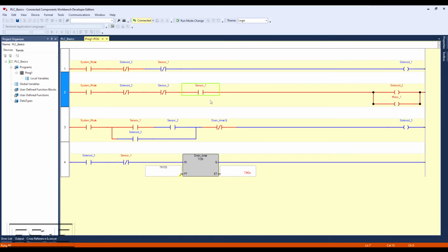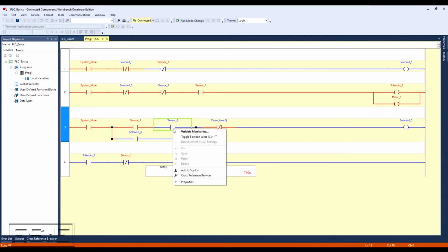Now we are mixing and adding our second ingredient into the tank. We are going to continue to fill until sensor 2 is turned on. When sensor 2 turns on, it will shut off all the remaining equipment and open solenoid 3. Our last step in our sequence was to leave the dump valve open for an additional 10 seconds after sensor 1 turns off. Simulating our scenario, sensor 2 will turn off first. The next condition will be that sensor 1 turns off.